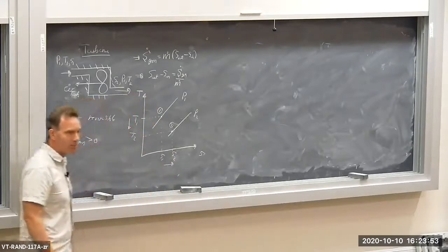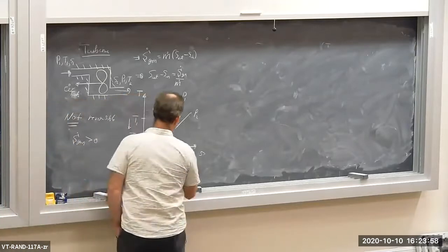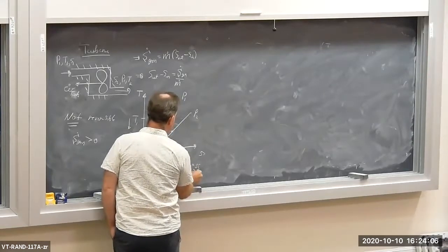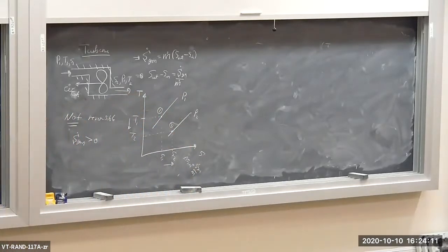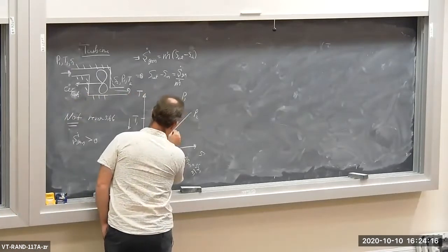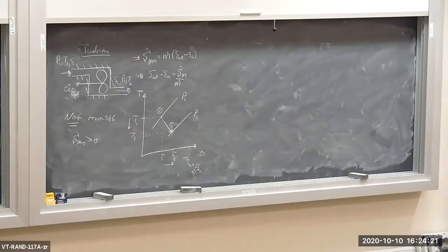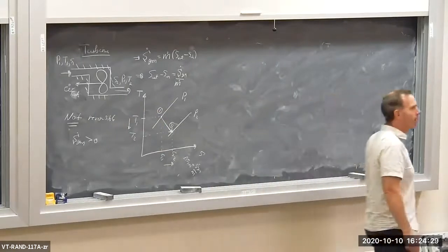So specific entropy also goes up. So this delta S from the inlet to the outlet is S dot gen divided by m dot for the working fluid. So the process looks something like this, for the air as it flows from the inlet to the outlet of my turbine. Okay? So that's what the process looks like for the non-reversible adiabatic turbine.